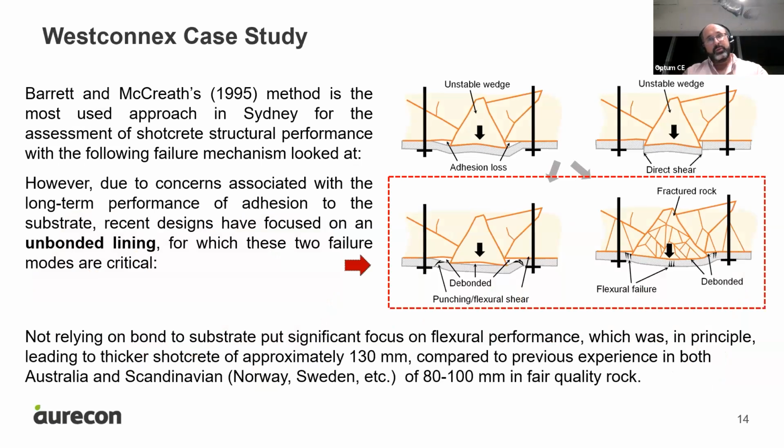And this good adhesion, good bond capacity, in fact, provides a lot of resistance for the lining. If I have good shotcrete adhesion, or sprayed concrete adhesion, to the rock, the only really kinematically feasible failure mechanism is direct shear. Because if the shotcrete is adhered to the rock with enough capacity, and this can be measured, we can measure adhesion because we can core samples and pull them out and test the adhesion,